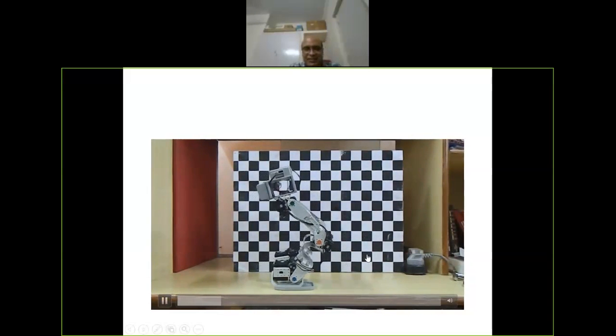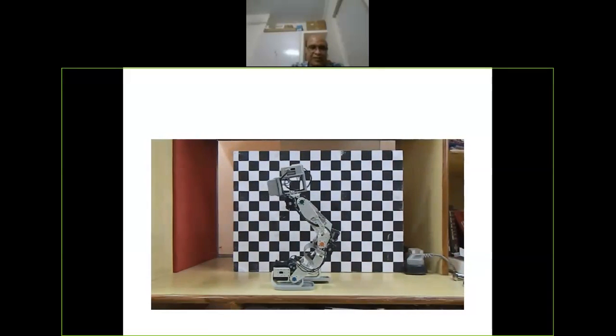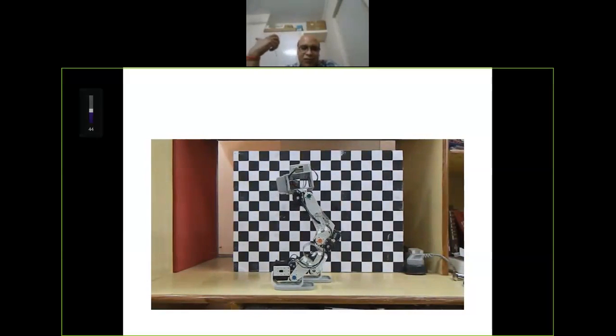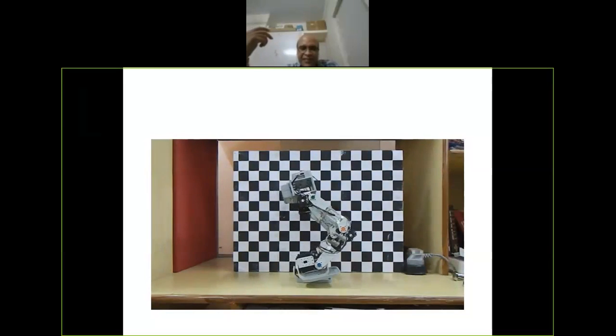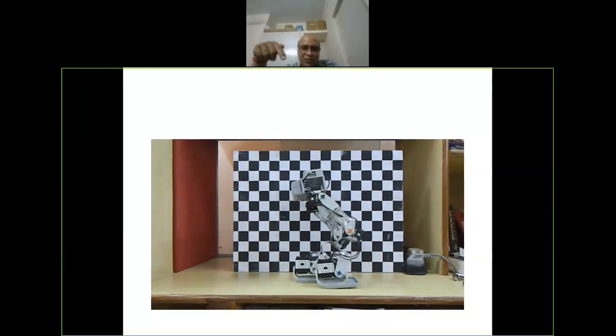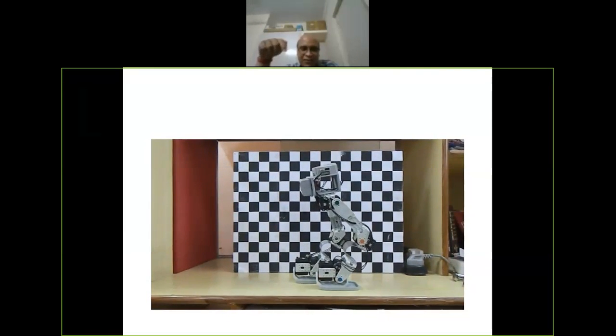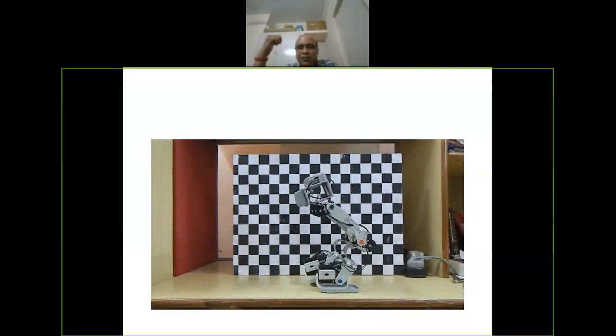So something quite interesting also is that in the human legs there is no vibration because we can actively switch the compliance or the stiffness. We can change it as we are moving. But this robot, because it has a mechanical compliance, cannot shift the compliance, and that is causing the vibration. So theoretically, we should have a compliance system in which we can actively vary the compliance or the stiffness of the system. Okay. Now that is still a challenge. We have not got that far, but these are some examples of mechanical designs and control optimization using stiffness.